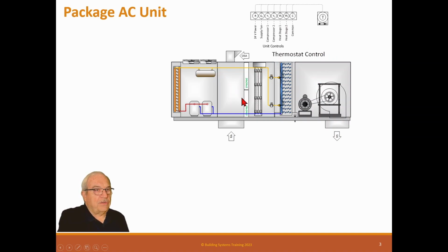Now the refrigerant circuit on this has two circuits. So what happens here is that we have two compressors. One stage, we go ahead and start a compressor. It takes the suction gas from the coil. It has two coils, so it's got supply piping and return piping, and the return piping, the suction for that coil, comes back to its compressor.